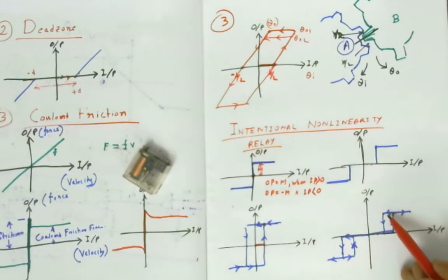Say now I am again decreasing my voltage, and at say 3.8 volt, it cannot attract the plate inside the coil. The coil is no more energized. So suddenly the output is off. Now again, if you increase the voltage towards 5 volt, it is on. If you again decrease your voltage, it is again off. So it is forming a loop, a hysteresis loop.